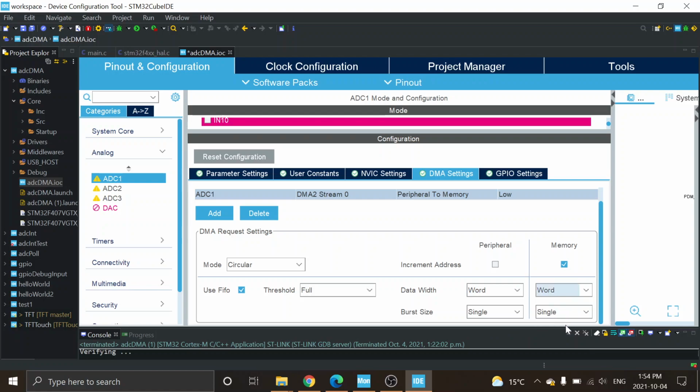The upper 16 bits are reserved. If we go look at the ADC register, the upper 16 bits are reserved. The data is actually coming back in the lower. Okay, you can put it, I'll show you where when you go and do it. You can put it as 16-bit values, and then you're using up less memory space. The library is just going to give you a little exclamation mark that says, are you sure you want to do this? Okay, so either way.